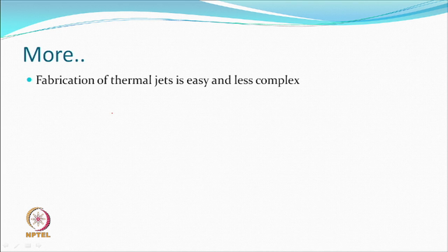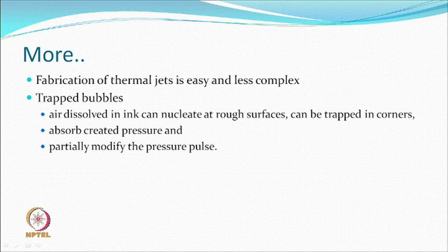On the other hand, fabrication of thermal jets is easy and less complex, and so you may get a large number of thermal jets also, but there are issues. Air dissolved in the ink. One is there is water which becomes steam, but you may also have dissolved air which can cause some problems.